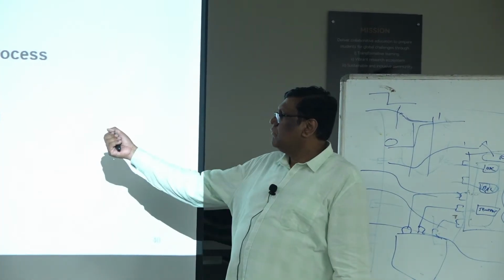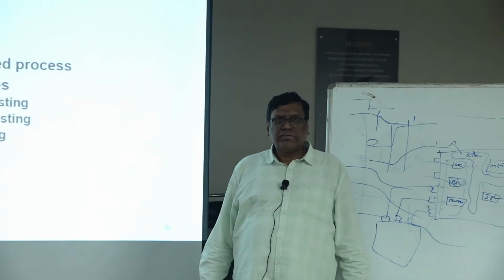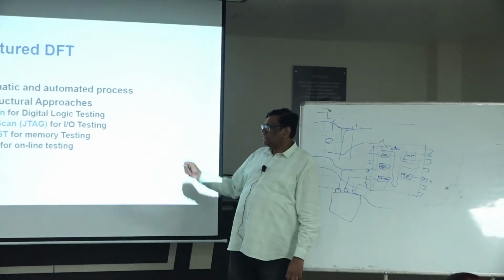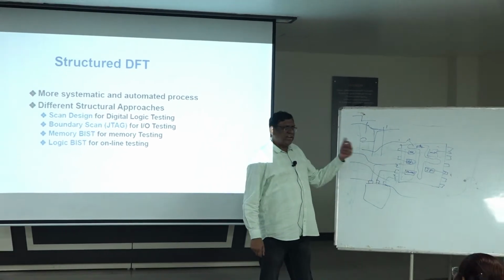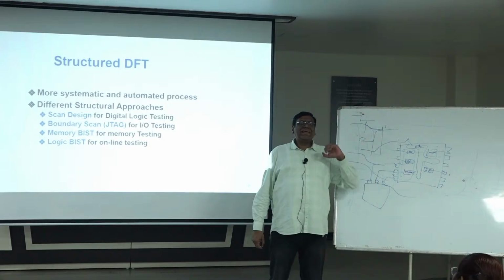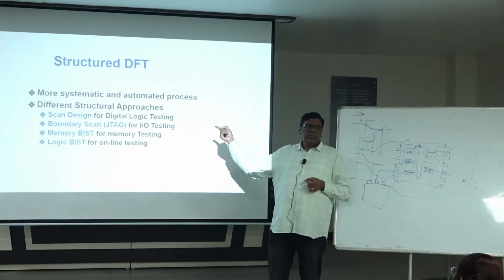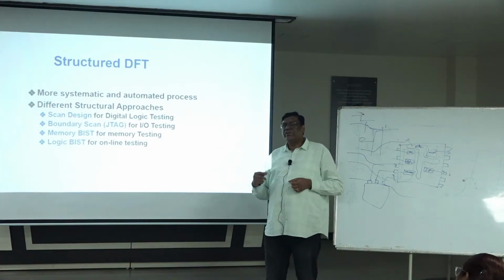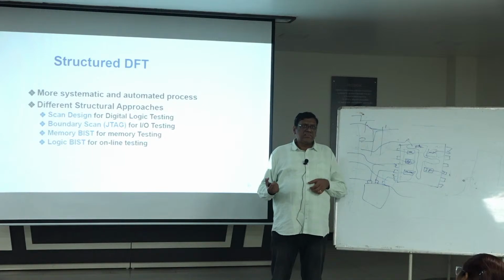The other technique is BIST. MBIST, memory BIST, is popularly called MBIST. The other one is logic BIST. Logic BIST is also very similar to scan design, but it happens in real time. Scan design will not happen in real time, but logic BIST will happen in real time, like automobile ICs.